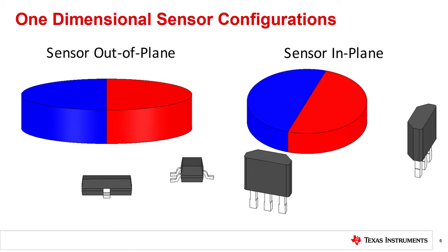With the second sensor rotated 90 degrees about the center of the magnet from the first, each sensor will be exposed to the same field over one full rotation with a 90-degree phase difference. This is a simple way to set up the required signals for angle calculations.